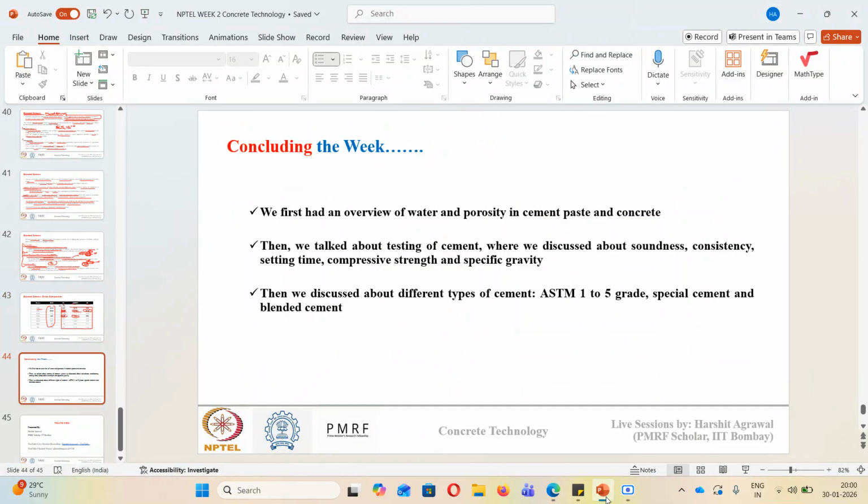Okay. So this was for today. We discussed water and porosity. We talked about testing of cement, where we covered soundness, consistency, setting time, compressive strength, and specific gravity. And then we talked about different types of cement: ASTM grade 1 to grade 5, special purpose cement, and blended cement. For blended cement, I didn't go into deep discussion because there will be a complete lecture on mineral admixtures where we'll again talk about blended cement and their reactivity. So today I just touched upon what blended cement means and where it originated from.